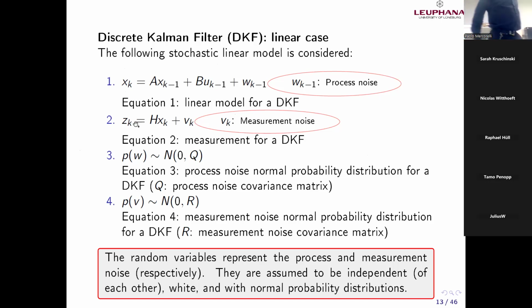The second equation is the equation of the output. In this case, we can consider, in this course, almost just measurements, but of course a part of the model can also be included in the second equation. In a more advanced Kalman filter, we can use this, in which basically without this V is exactly what we have seen until now. Instead of H, we had C. Instead of Z, we had Y. I changed nomenclature because we have two different nomenclatures, one for Luenberger in the literature, one for the Kalman filter.